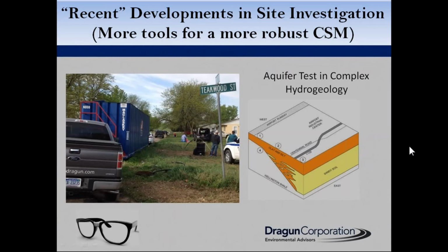This is a site that we're working on currently in the middle of the United States. It's a very complex Cold War era legacy site where we have a definite deadline and an important mission, and that mission is to protect the health and environment in this community of 50,000 people. There's a massive amount of TCE in the subsurface, and there are over 10 plumes, some of which are thousands of feet long. They move into residential, commercial, and educational districts.